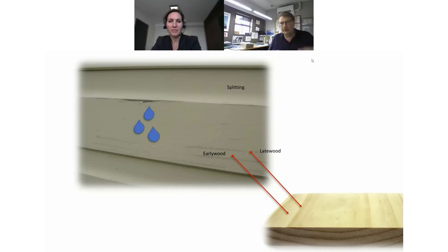It's a flat sawn board. It moved quite a bit, but up until now, we've been talking about the total movement of the board. But do you not think that bits within that board have moved a little bit more than other parts of the board? And they have, so keep your eyes on the screen, because the entire board is moving, but the late wood moves a little bit, but the early wood moves a lot, and then you get those splits right there. So after everything you've learned today, you could simply see what is causing those problems.